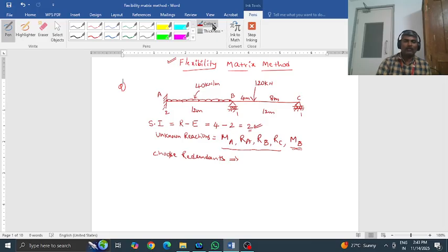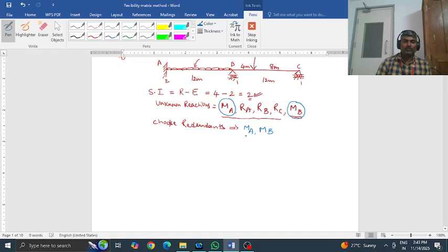Now I'll choose MA, MB as redundants. You may choose any 2 from these. So I have chosen MA, MB as redundants. Now I shall assign coordinates to the chosen redundants. I call MA as 1, MB as 2.